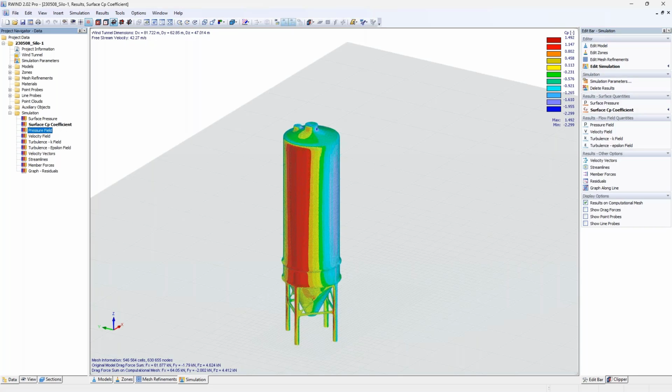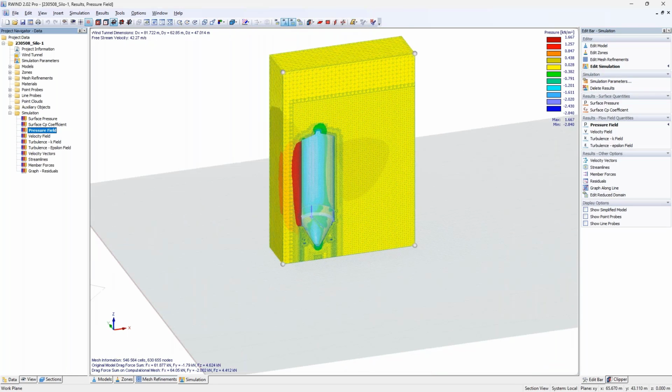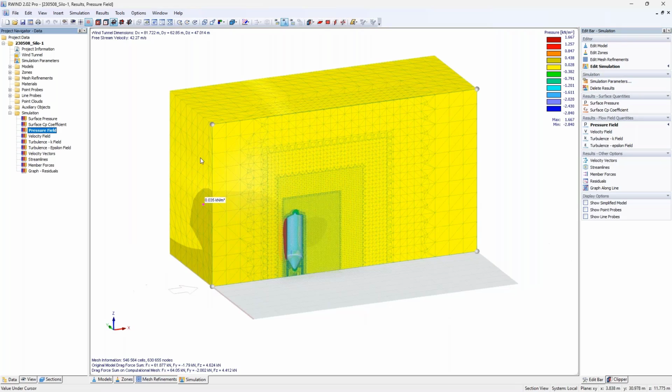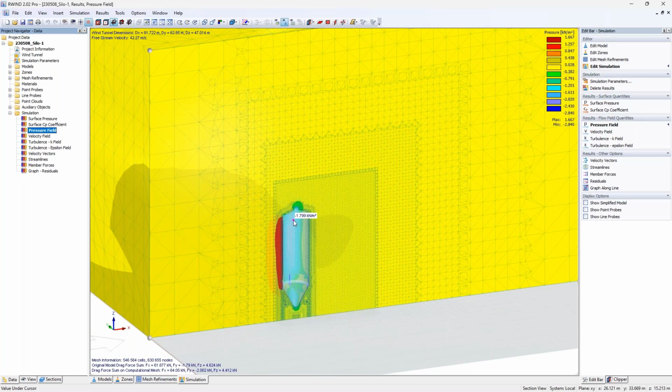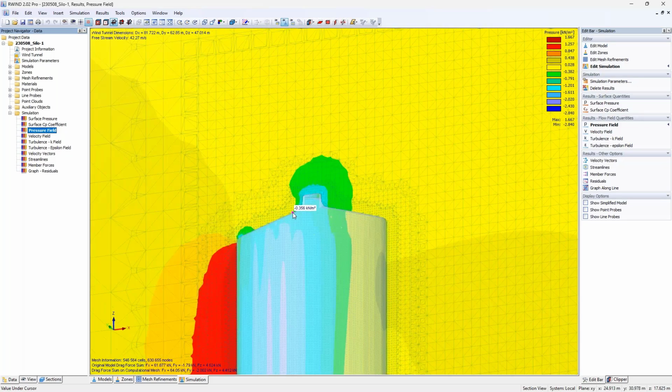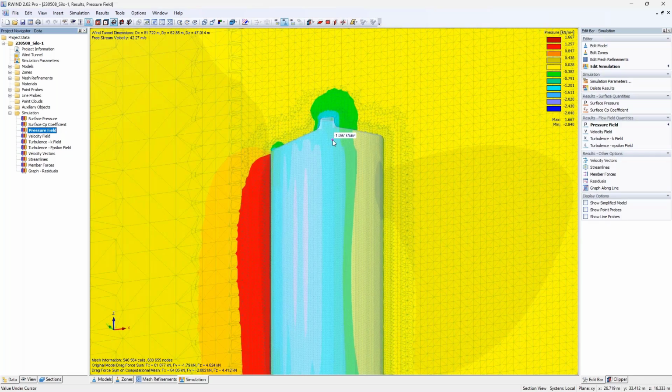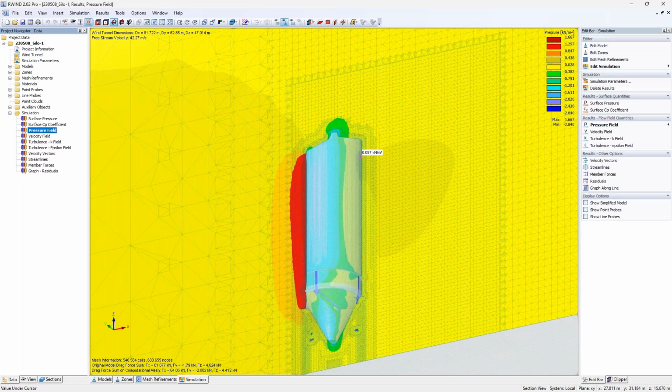So let my computer shortly load it. And this will represent, of course, the solids in the pressure field and their results. So as you maybe can imagine, by reducing the reduced domain to show the full wind tunnel, this is our full wind tunnel with our, let's call it, small model. You can see that the main effort is, of course, to have a mesh as small as possible, but it needs, of course, to interact with the boundary of the model. So it needs to be refined around the model. This is done automatically if you want it.